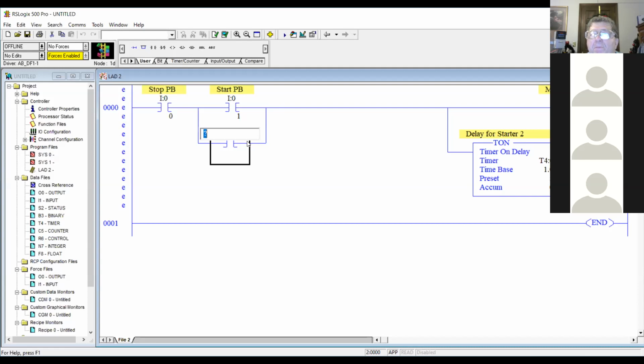Wouldn't it be I02? What if you're going to have the holding contact to be controlled off of that right there? Oh no, yeah, it would have to be the same. Which would be O, and then 0/0, and when I hit enter, it actually picks the same name. You see how that popped up? That's neat. That's in the database. That does make it a little easier.